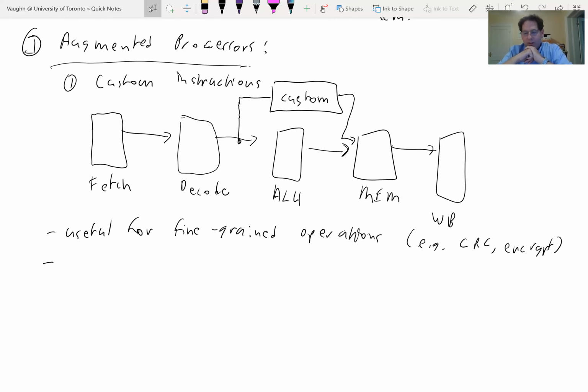Why couldn't I just make an instruction that takes 100 elements from a row of a matrix, scales them, subtracts them from maybe the next 80 rows underneath it? So I just encoded a huge amount of computation. Why does that custom instruction not work very well? Let's see. Complex operations take too many cycles to operate. Yes, those are good answers. It's not that I couldn't, and we're going to see other ways to organize that, but basically it doesn't fit into this custom instruction very well, because this custom instruction is basically too closely coupled to the soft processor pipeline.